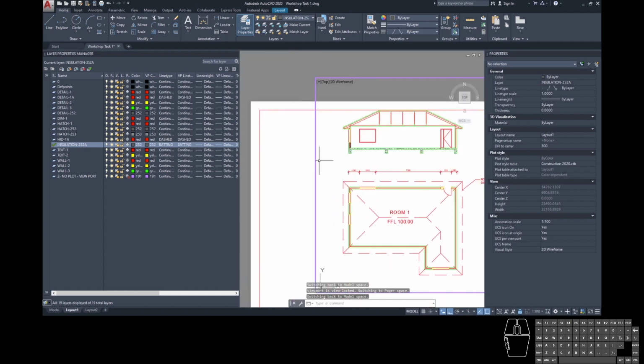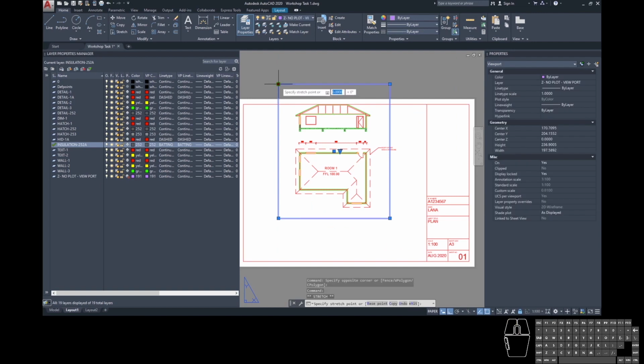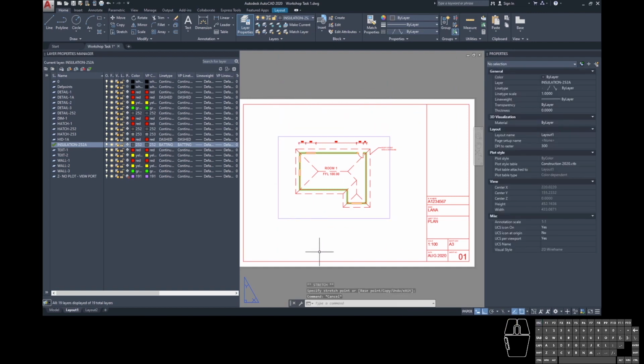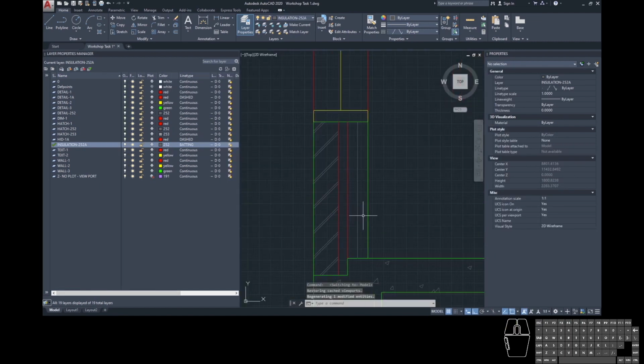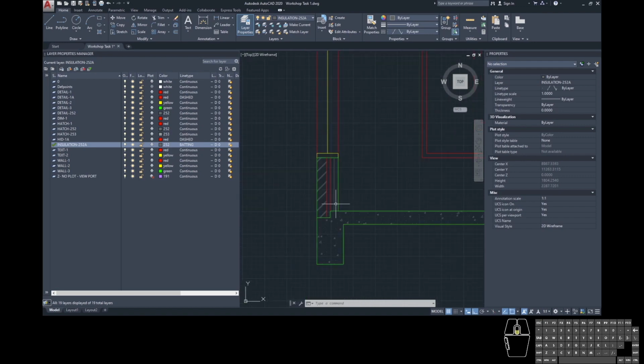When we come back out again, I'm going to deactivate that viewport, bring it back down to where it was before because I don't want to see it on my sheet 1. When we come back to this in model space, we don't see the wiggle in model space, but we know that we can see it in paper space, and that's the important spot because that's the way it's going to print, and so we don't mind that we can't see it here.